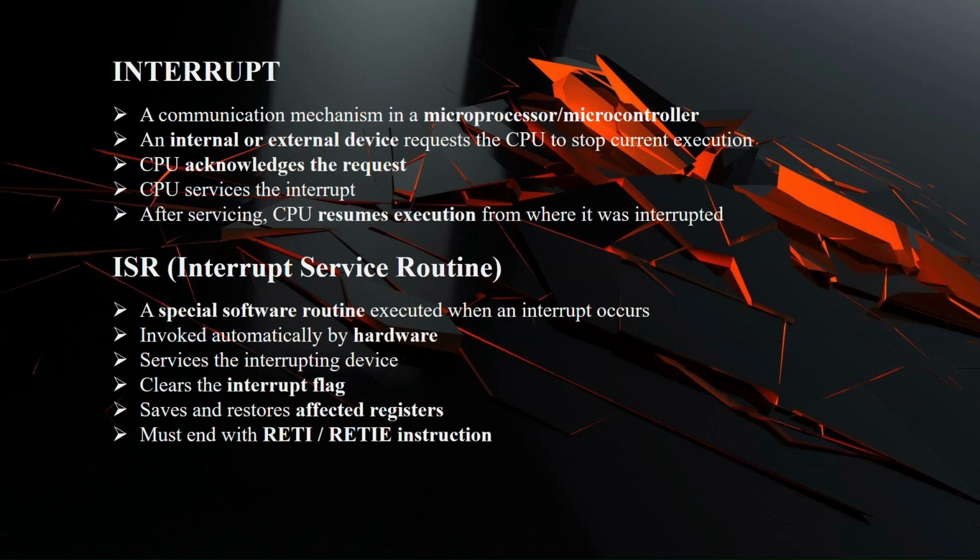The interrupt service routine is a short and fast routine that handles specific events such as timer overflow or a key press. After completing the required task and clearing the interrupt, the microcontroller returns to the main program and continues execution. The ISR is essential in real-time systems because it ensures quick and accurate response.